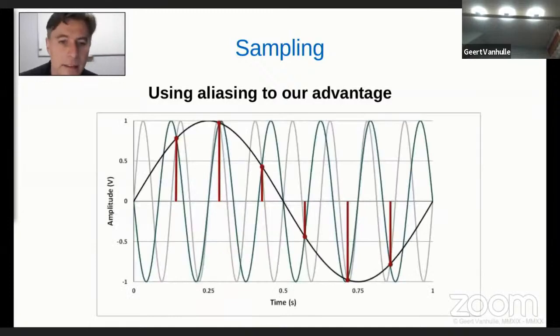Now, if we look at aliasing in general, for any given sample range, so the red here are 6 samples, there are an infinite number of sinusoidal waves that we can draw exactly through these sample points that would exactly produce these samples, and thus the discrete sample results cannot tell anything about which one of these frequencies it is.